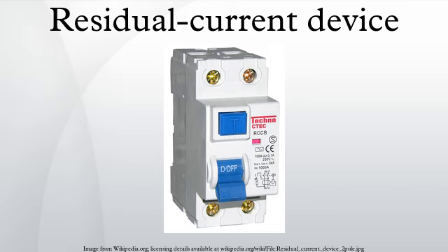Limitations. A residual current circuit breaker cannot remove all risk of electric shock or fire. In particular, an RCD alone will not detect overload conditions, phase-to-neutral short circuits or phase-to-phase short circuits.